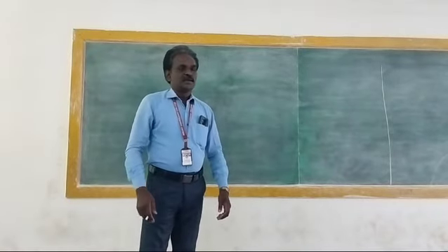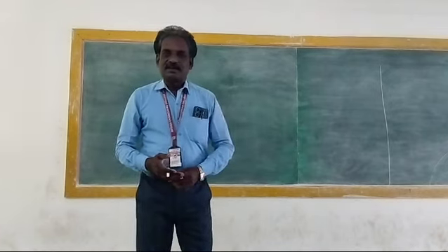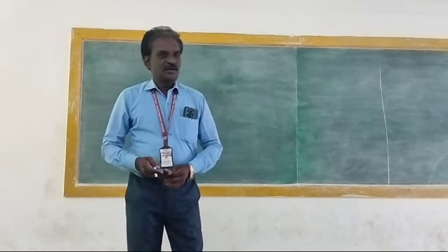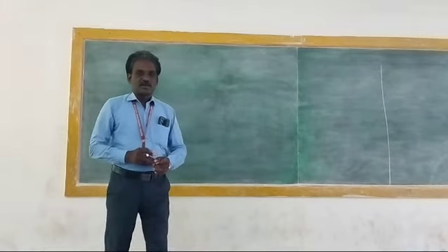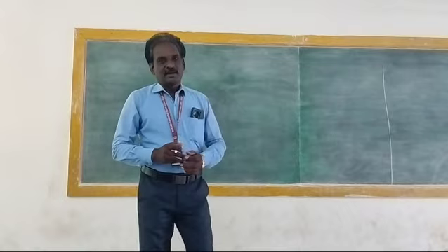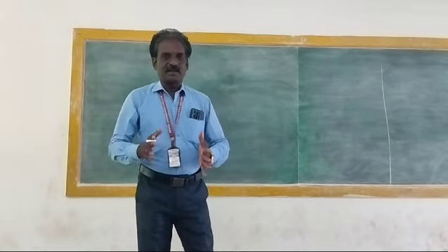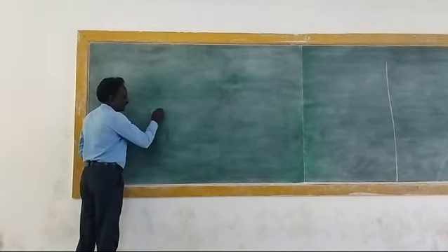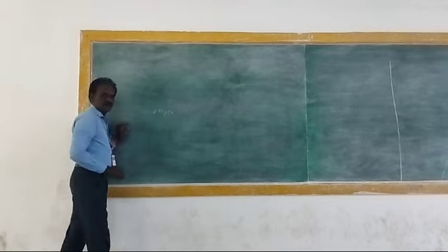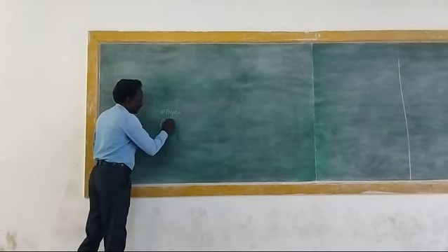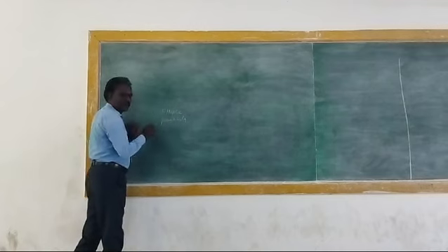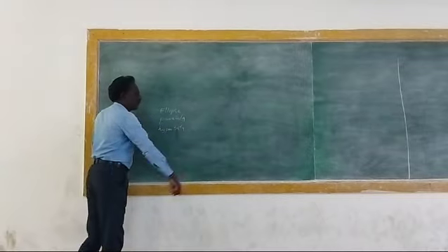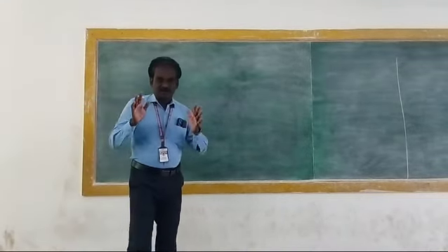Dear students, in this class we can see the construction method of engineering curves. As we know, the curves which are used for engineering applications are known as engineering curves. Mainly in our syllabus, we have three curves majorly: ellipse, parabola, and hyperbola. The construction method is same for all these three curves.